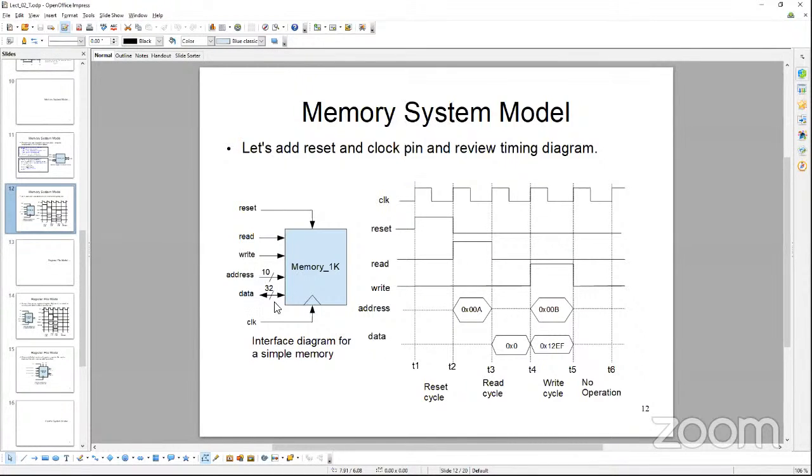Why? Because we are using the same electrical physical data line: memory is giving out the data and the processor is consuming that data at the other end. The processor obviously cannot use the same line to send the write data to the memory at the same time point, so they need to be separated in the time domain. Other than that, if it is a consecutive write or read, or even a read after a write, we don't have that constraint anymore, and we can operate normally.